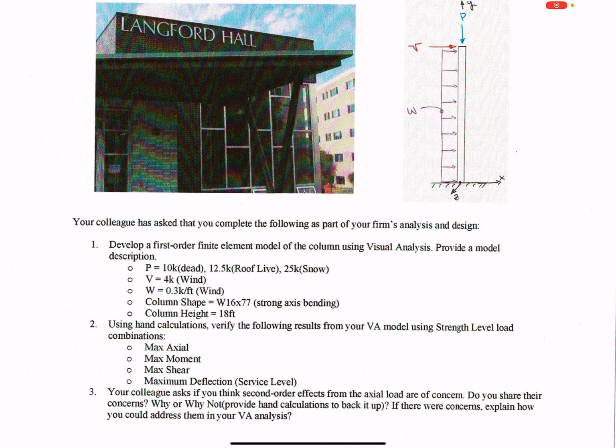Wind load's interesting because when they do service level for wind, we multiply it. What's the factor we put on it when we do wind loads at service level? 0.6. Service level, 0.6. Because we calculate wind at strength level.